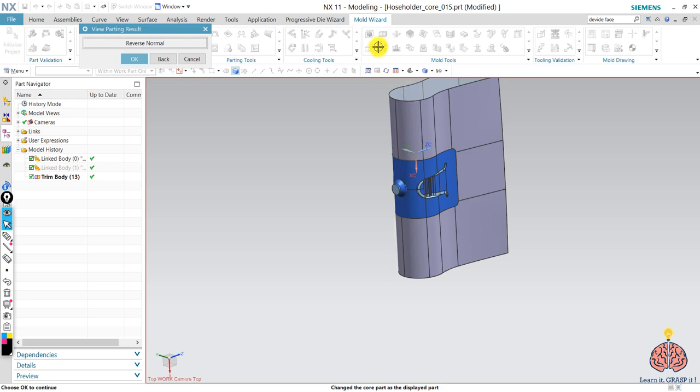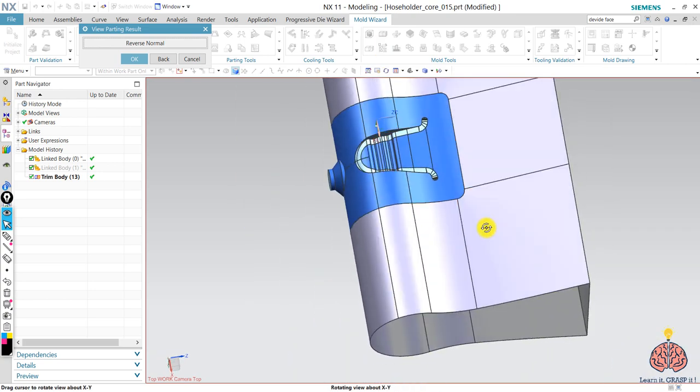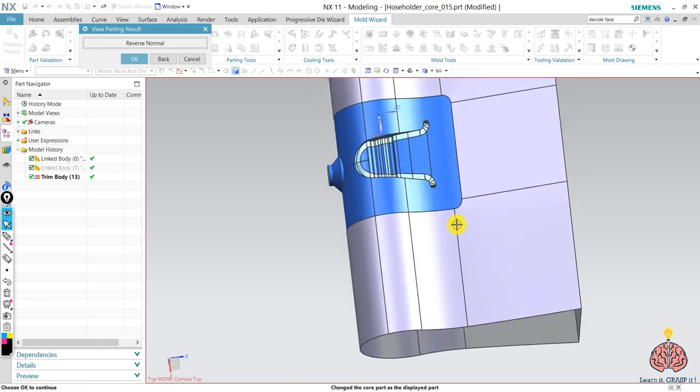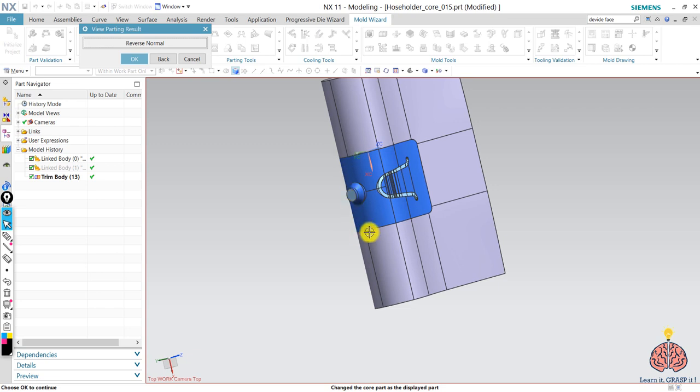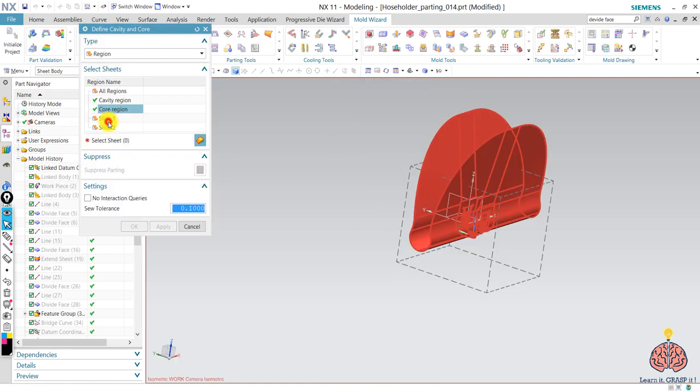So it will come from here. And as we said, as the core is going out, it's going to spring the material out, and then when the core gets totally out, the material will spring back in, returning to its original shape. Right, then we made the core successfully.